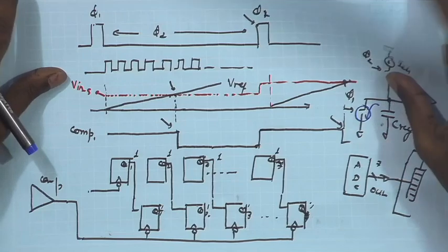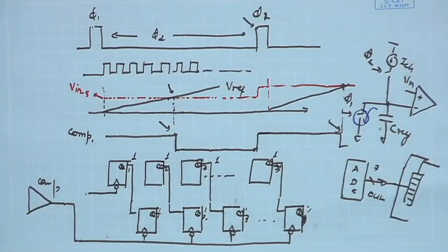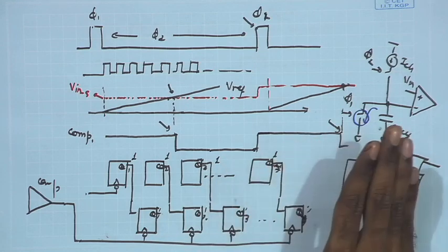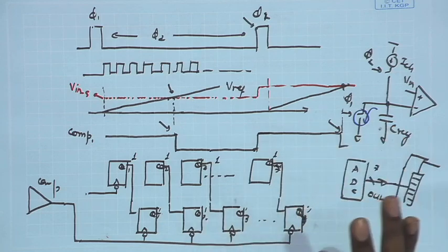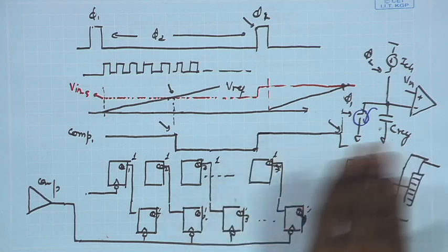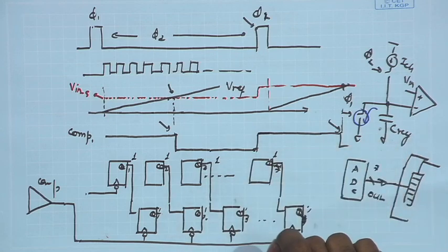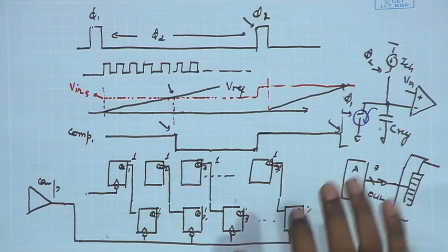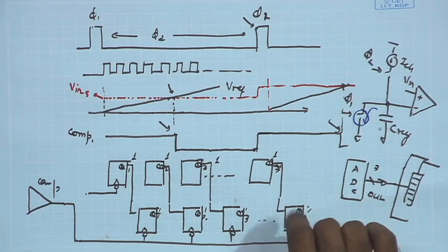Of course, for the other two circuitry, the sampling circuitry, we have to look at the sizing of the switches. As we saw in the sampling circuitry, the sampling switch size is going to determine the RC time constant, and we calculated that the minimum size transistor was also expectedly meeting our RC time constant quite comfortably. So there the switch sizing was not very critical, provided we are using few picofarad of sampling capacitor.